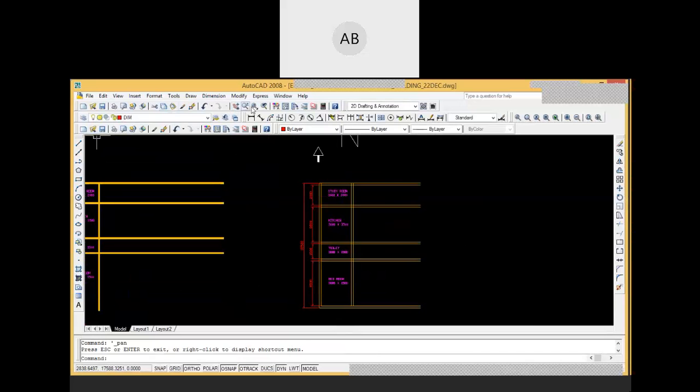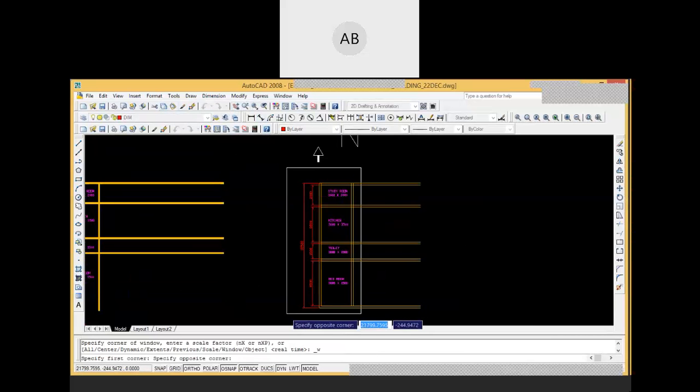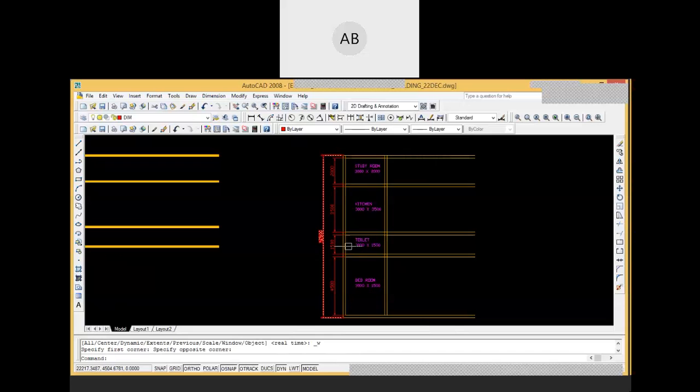If you use a polyline with the thickness, you will not attain the overall length and breadth that is mentioned in the drawing. So rather, use two single lines in order to show the wall thickness. In this case, we are assuming a wall thickness of 200 millimeter. Here, what dimension is showing is the plinth dimension.